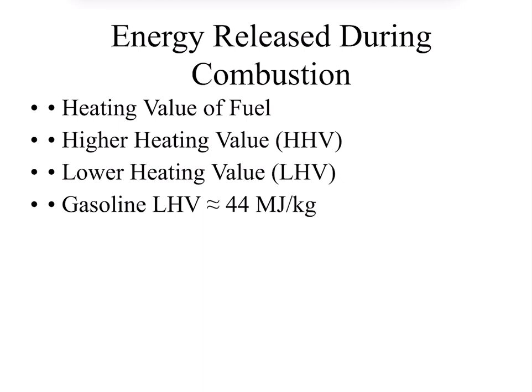And then next we have energy release during combustion. The energy released during combustion is quantified using heating values. HHV includes the latent heat recovered from water condensation, while LHV assumes water remains as vapor.